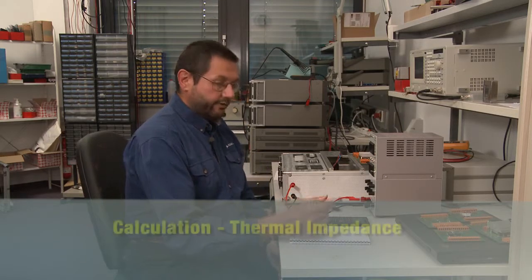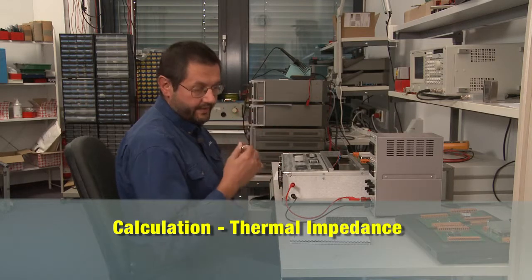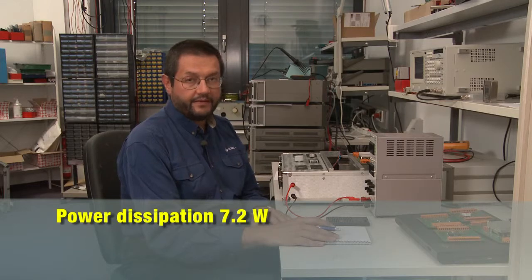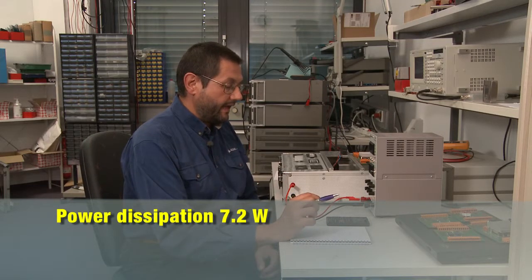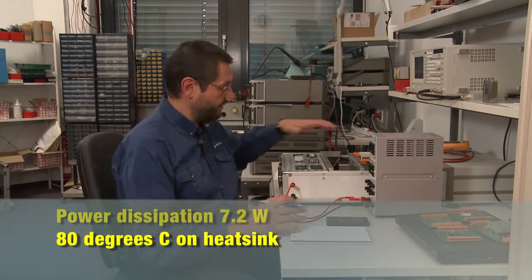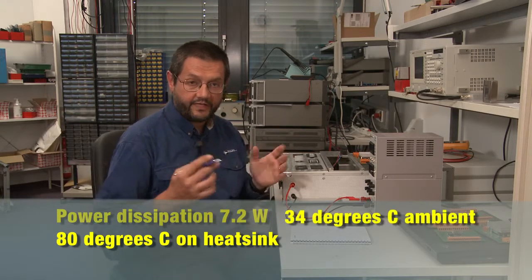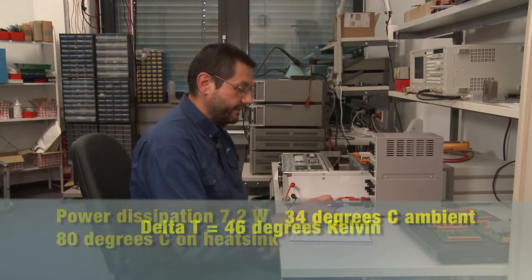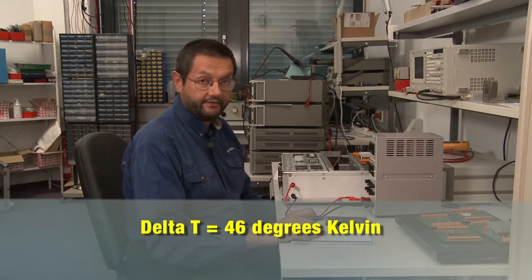What we can also calculate now is the thermal impedance of our system toward the ambient. The power dissipated is 7.2 watt, and we had a delta temperature increase, which is 80 degrees C, what was reached on the heatsink, minus 34 degrees C, which is the ambient temperature at which we run the experiment, gives us a delta T of 46 Kelvin.